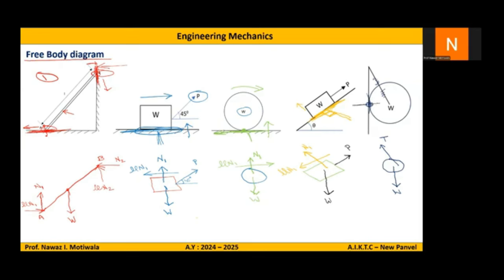And the direction will be from the surface to the body, so it will be like this. So transferring the force here, I get this as the force and I will name it, let us say, N1. Now, regarding the friction force, because this body is not moving with respect to any of the surfaces, there is no friction which will come into the picture. So this completes the free body diagram of the object shown.